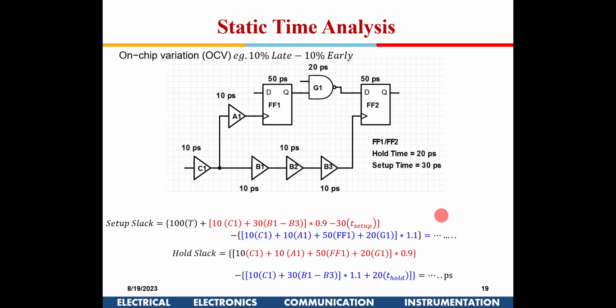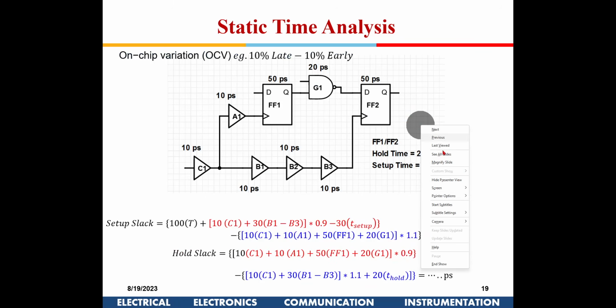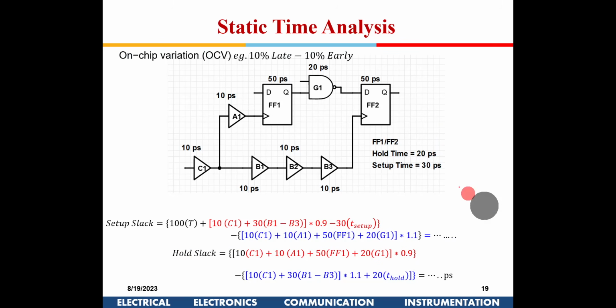Every part, you have to analyze if there is a hold and setup violation in each flip flop. There could be one more flip flop here where this Q bar is going, through some combinational block, and it is going here, right?